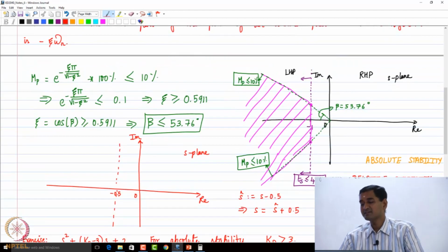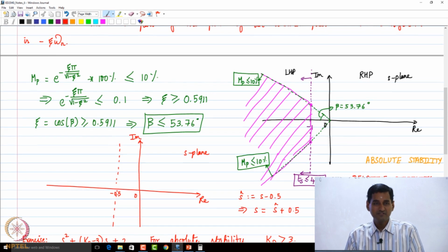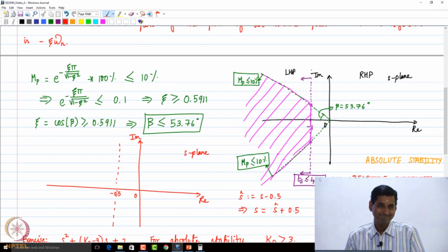See, what I mean is, let's say you have a 10th order system, for example. You need to design a closed loop control system which is of order 10, but still I can always say, look, I will specify performance in this manner. The reason is the following: we have explicit expressions for specifying performance specifications for systems of order 1 and 2, and by and large the dominant dynamics is going to be that of that order, right?